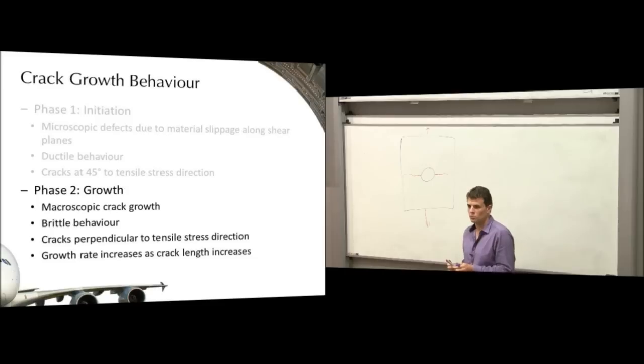It's actually a power law because the proportionality isn't linear, but it accelerates. So the cracking, when the crack is small, grows very slowly. When the crack gets bigger, it grows faster, and eventually it reaches a catastrophic crack growth speed, and we apply some load, and the crack will just propagate off to infinity, and the part will break into two pieces.